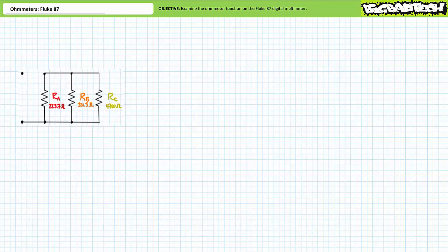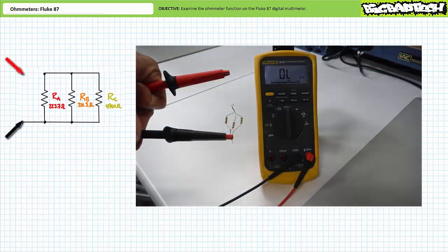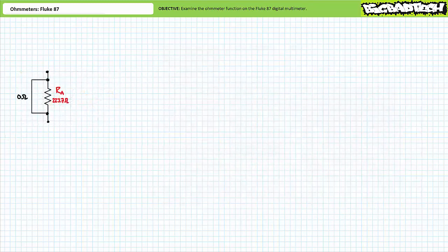Consider the parallel combination of A, B, and C, where the entire parallel combination is dangling out in space. The ohmmeter demonstrates that this parallel combination now presents an infinite resistance because the open has severed any and all paths through everything. Let's now deal with shorted elements inside parallel circuits.